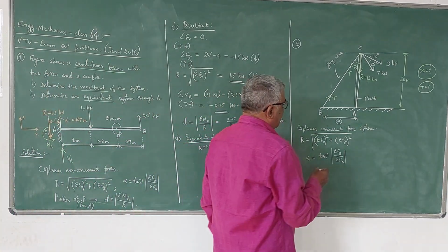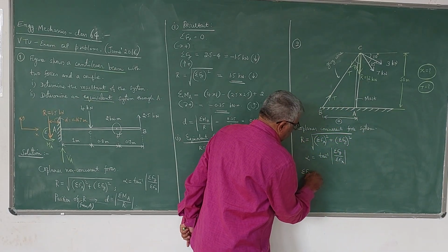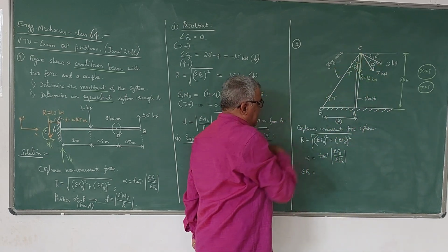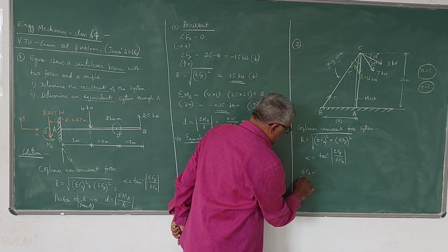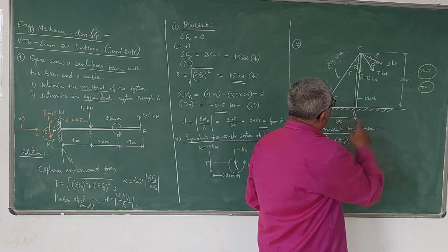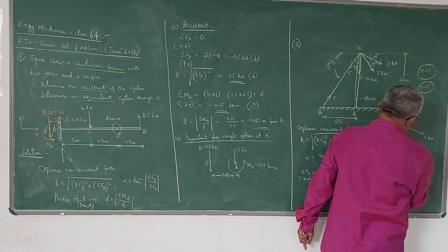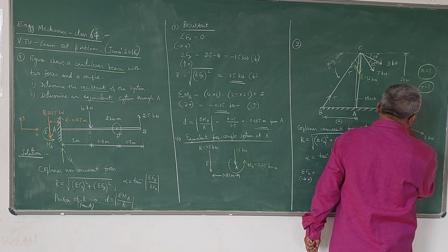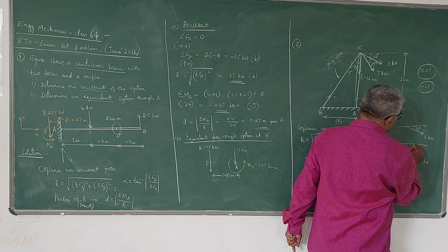Let us calculate sigma Fx and sigma Fy. So these three forces I have to take. The resultant is acting vertically downwards. So for sigma Fx, I will take forces acting towards the right as positive, that is the sign convention. So we have to resolve these forces now. The 3 kilonewton force I have to resolve, then the 7 kilonewton force also. With respect to the horizontal, this is 10 degrees. This is 10 plus 25, 35 degrees.